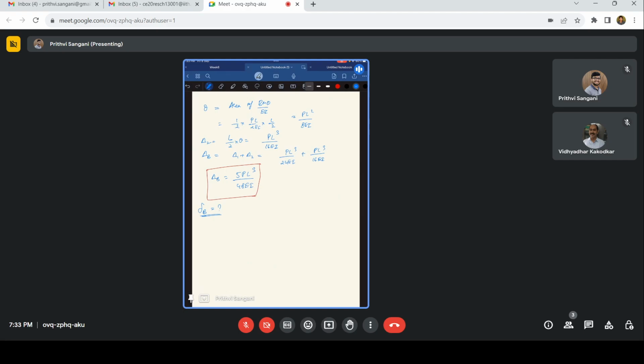What happens to VA? VA has to actually counter this, as there is extra bending moment generated there. So if you check for VA, again without support settlement, this is 10 into 12 into 12 by 12, which is 120 kilonewton meter, and VA is going to be 60.